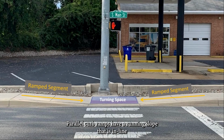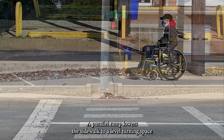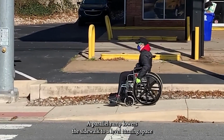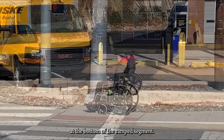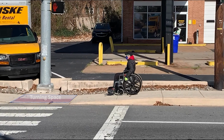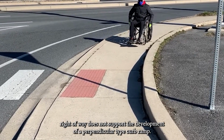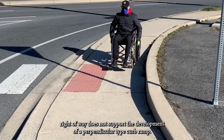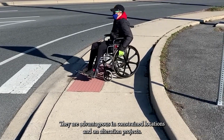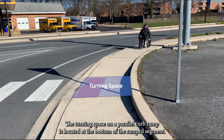Parallel curb ramps have a running slope that is in line with the direction of sidewalk travel. A parallel ramp lowers the sidewalk to a level turning space at the bottom of the ramp segment. This is where users maneuver to enter the pedestrian street crossing. Parallel curb ramps are primarily used where the available right-of-way does not support the development of a perpendicular type curb ramp. They are advantageous in constrained locations and on alteration projects. The turning space on a parallel curb ramp is located at the bottom of the ramped segment.